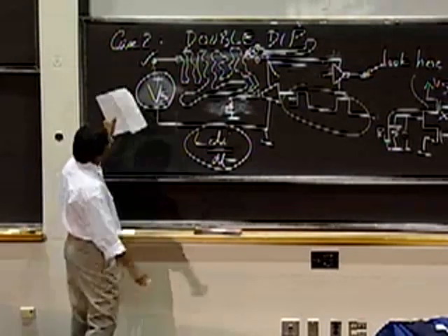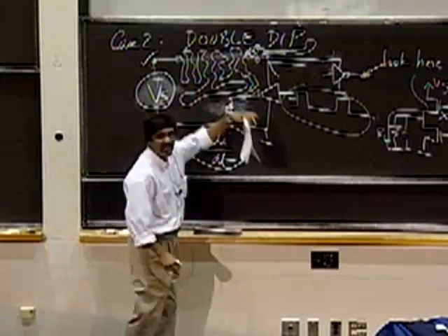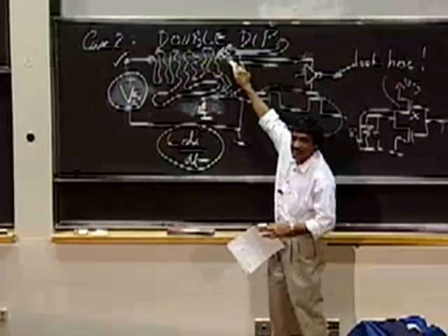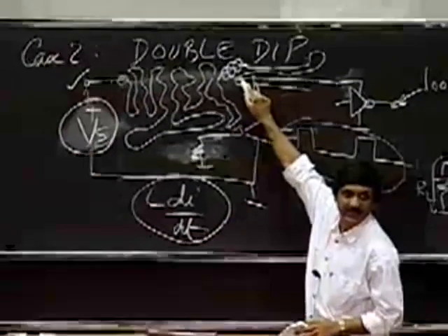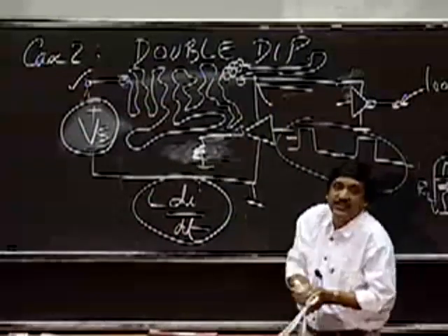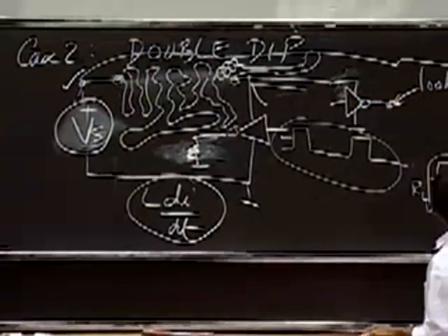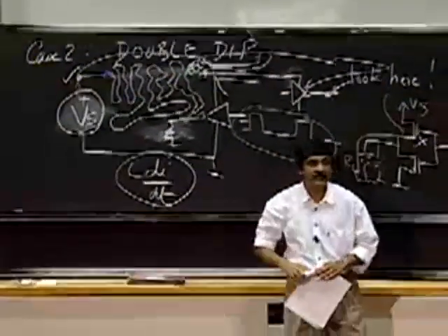I could do that. So what I could do is use different wires to connect each of the inverters. That's a good point. Here the coupling happens because I connect the two inverters way out here. So instead I use a different cable. I hadn't thought of that. That's a creative solution.